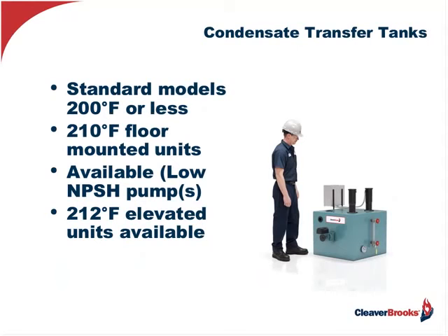What you're looking at here is a pump and tank assembly, a package, normally used where condensate does not exceed 200 degrees. There are some that can be purchased that will be able to accept 212 degree water, liquid. These are also constantly venting, so if there's any flash at all, it will vent out. I want liquid. I don't want a biphase to be hitting these pumps.